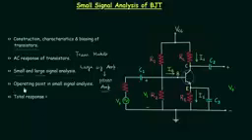Now we will talk about the operating point in small signal analysis. By using a small signal, we do not have to worry about the operating point, because if we use a large signal, the base current IB will also increase, and we already know the collector current IC is equal to beta times the base current, neglecting beta plus 1 ICBO.